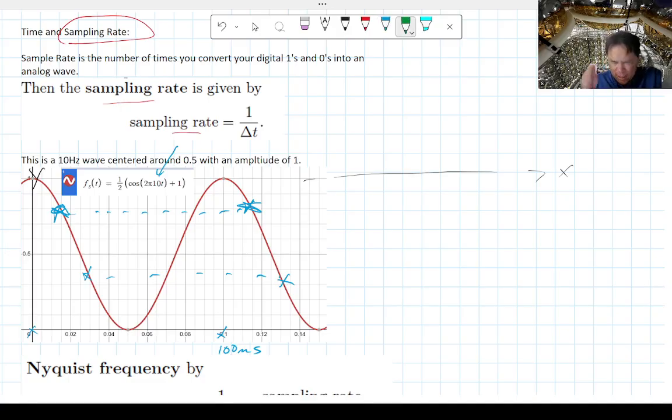What you want at least, okay, is to maybe sample the wave at least twice per period. So let's say, I'm going to do this in green. I do this in the beginning here, maybe at a very similar point, right? This green here. Okay, half a period later, it's around here, right? And then another half a period later, it's going to be around here, right?